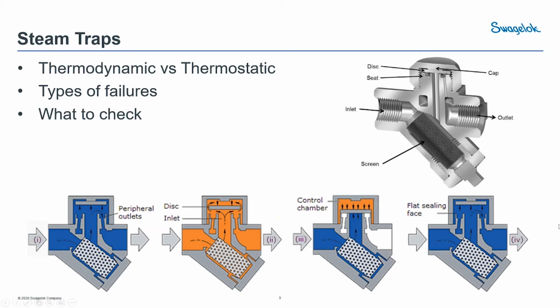On all your traps, you should expect them to relieve a little bit of steam condensate with a little puff of steam and then stop. And they should relieve and stop and just cycle like that over and over again. The frequency might be longer. It might relieve for even a full minute and then stop for a full minute. So you'll have to watch it for a while to see that frequency.